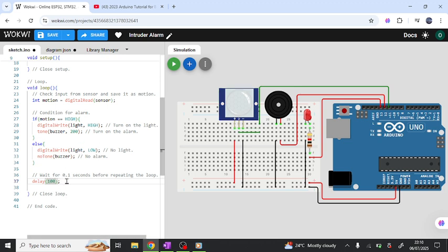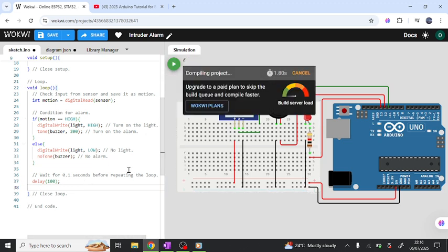But if we remove this delay, the Arduino, after taking the input, will not wait for any time. It will go again to the sensor, collect input again, run this one, go again, collect input. It will not wait. We're just saying that at least maybe hold a little break. Alright, so let's simulate this and see what happens, and then we'll close the loop, of course.